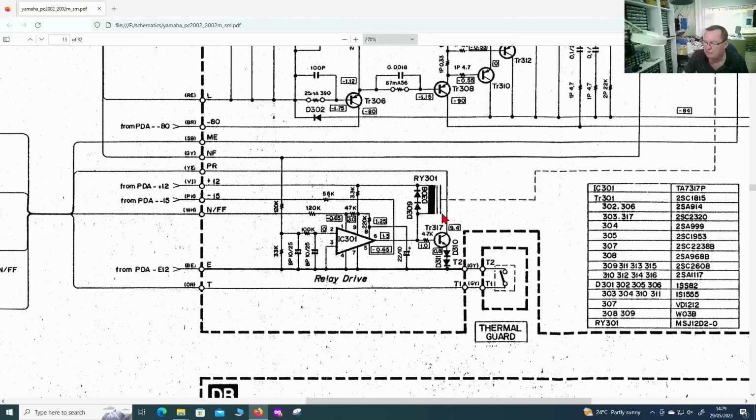When the transistor is conducting, you will have a voltage drop across the 2 diodes of about 0.5 volts each, 0.55, something like that. So the emitter will be at about 1.1 volts, somewhere in that region. Okay. The collector, because the transistor is turned on, voltage on the base, is also at about that 1.2 volts or thereabouts, 1.1 volts. And that connects to the protection LED.